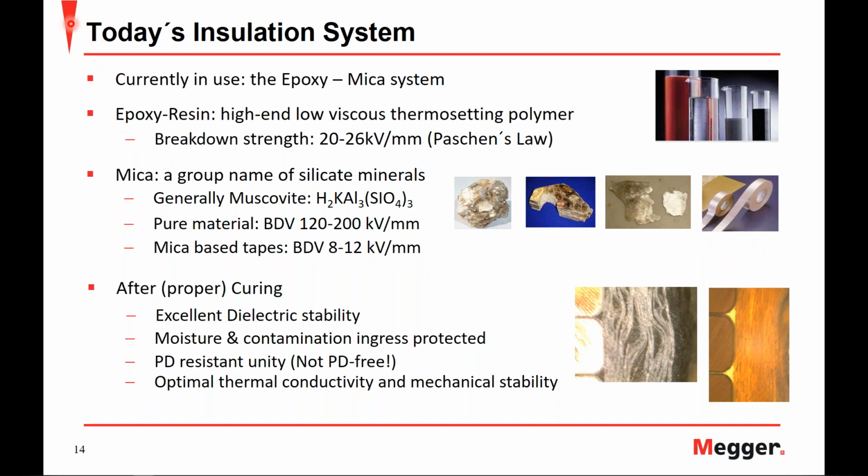Now, after the proper curing, these mica-based tapes provide excellent dielectric stability. They provide moisture and contamination ingress protection. They are PD resistant and have optimal thermal conductivity and mechanical stability.